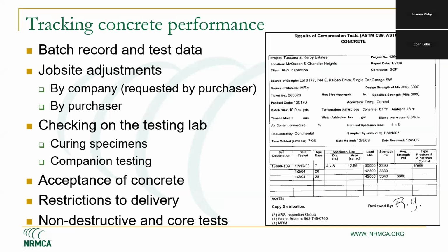Try and keep the batch record and the test data together so you can see the impact of your batching on your test data. Also make sure that there is some record of the job site adjustments. Make sure that your driver is aware of what the proper practices for testing concrete are so that they can observe what happens at the job site as to how your concrete is tested, both for fresh concrete properties, how those cylinders are made, and how those cylinders are cured before they are transported to a lab.